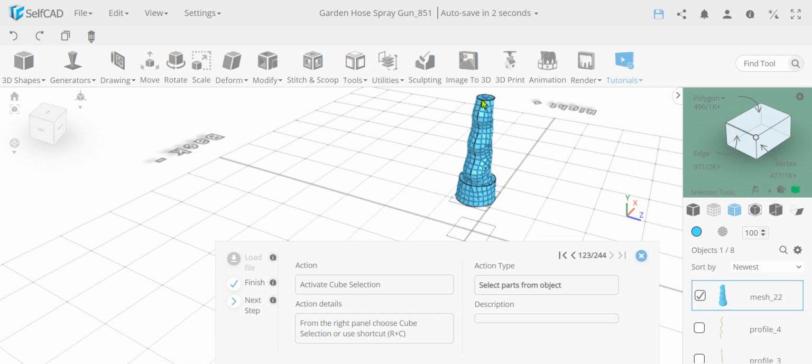So for example, if you had clicked on top and connected the rail, and then clicked on the bottom profile and snapped the rail to it, basically drawn the rail correctly, but skipped the center profiles and not connected to them, this will not work because we cannot automatically connect them. So basically, yeah, that's the idea. You need to connect them, but you can leave off the ends and SelfCAD will fill them in.